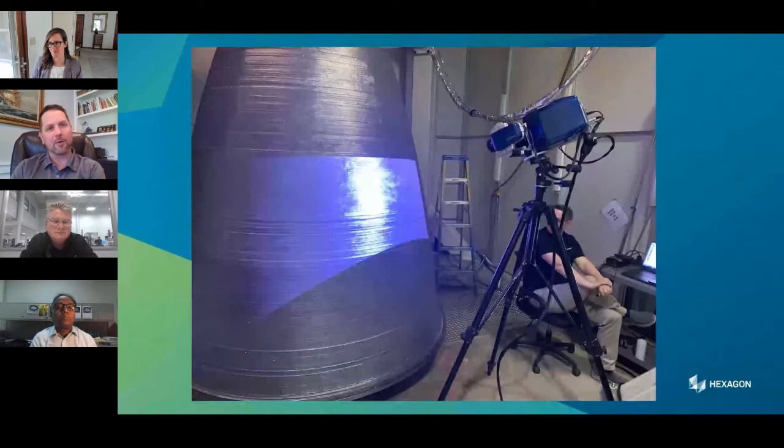And if you go all the way to one end of the spectrum, it's fully transient, like it's going to match every bit of movement of that G code. And if you go all the way to the other end, it's going to apply an entire layer all at one time. And so then essentially you can tweak that knob up or down and go from fully transient scan vector level all the way up to layer wise.